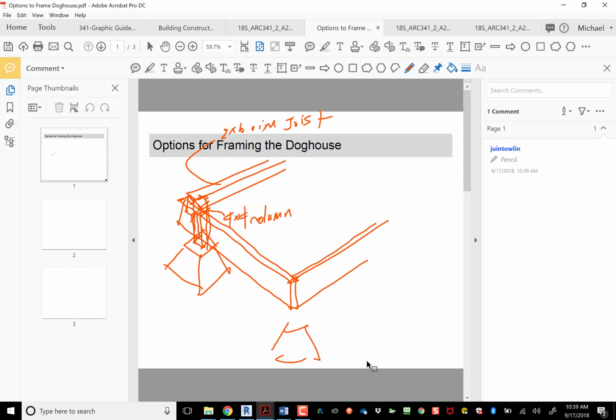And then basically this rim joist would support your floor joist, okay? So what's happening in the detail is that you have your pier block here, and then you have your hanger here. You have your standoff right there. You have your column. It has to come up above that because these are metal plates that have fasteners through them.